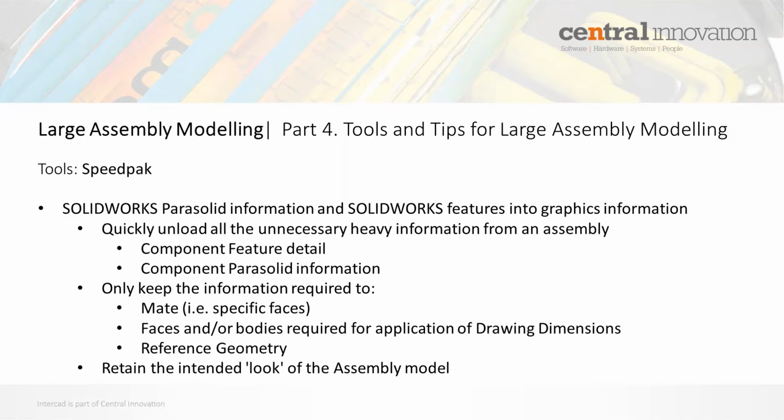So in previous webinars, I discussed Parasolid versus the actual tessellation that's carried with the model. With the SpeedPAK, it's only the tessellated data that you're actually seeing in most cases.